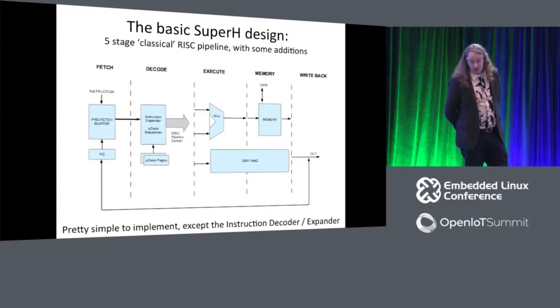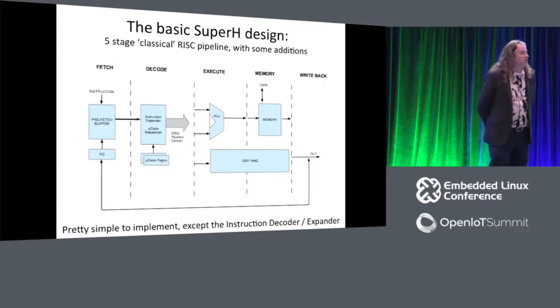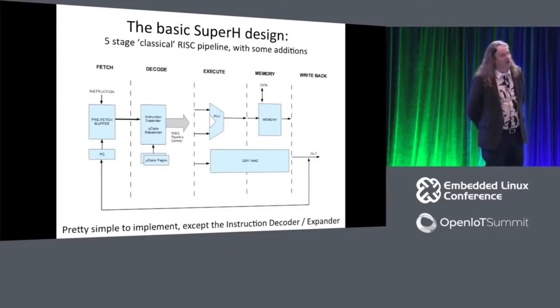And there are 3 implementations in the source code for the microcode. There's random logic, which works very well in an ASIC. We have a little ROM that maps lovely to FPGA primitives. And there's a reverse table, which is kind of like a big set of case statements. And this is the bottleneck for the speed of this particular device.